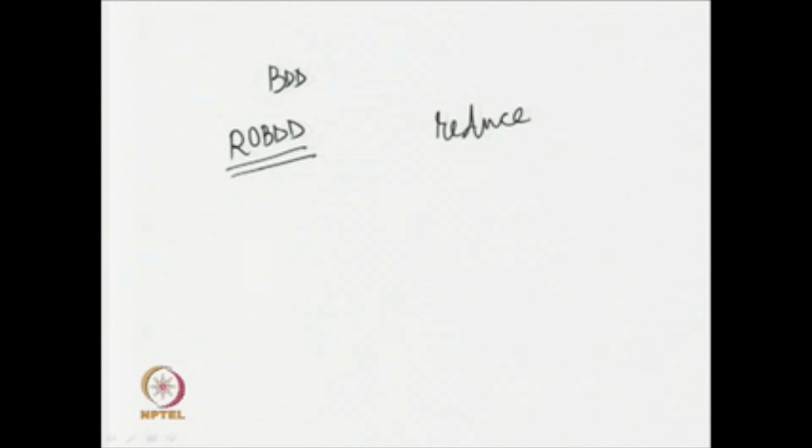First, we have seen the BDD, binary decision diagram, then eventually we came to the ROBDD, the reduced ordered binary decision diagram. Okay. Now, what will happen? We are going to get a unique representation of this ROBDD for a given function. So, to work with those ROBDD representations, we have seen some algorithms. So, what are the algorithms? First algorithm we talked about is reduce. With the help of this reduce algorithm, we can get a reduction of a given BDD, say B f. It will return me these things.